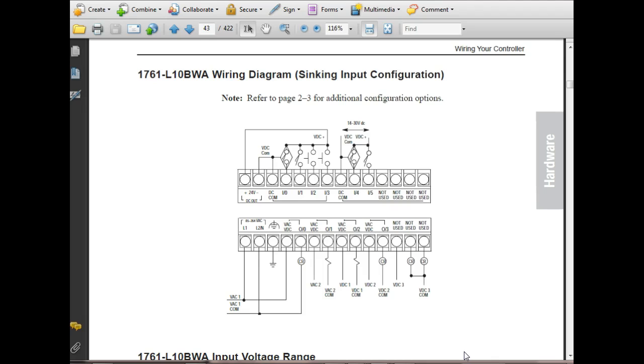Whatever you want it to do, source or sink. Right? So here's the power supply that you hook up to your input. So your inputs power off the internal power supply of the PLC. Here's the DC common here for these 2. And of course, this does not say sinking. It does not say sourcing, because you make it what you want.